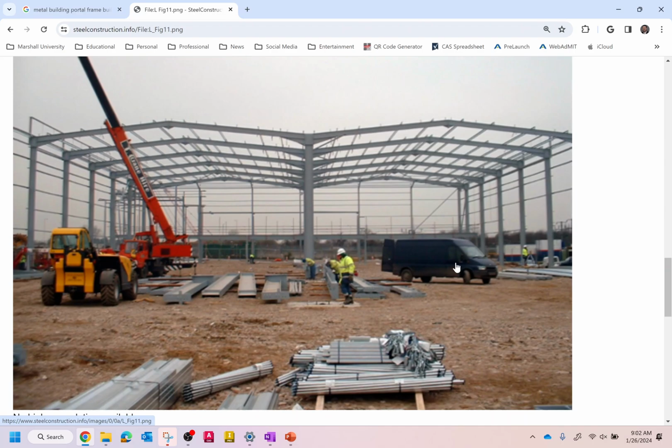right? So imagine wind is pushing the structure from left to right, and it's these tension rods right here, which we are going to do threaded rods in a little bit, that are keeping the structure stable. And so what would happen if you started getting a really, really slender element is you would see that this thing would be sagging a little bit. That's kind of what that meant. That does not mean the structure is going to fall down and kill people, but it does mean that it's not performing its intended function.